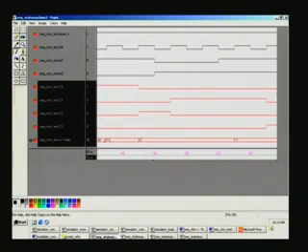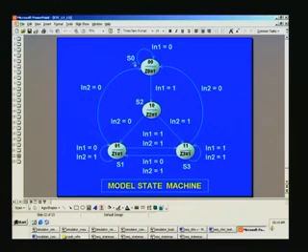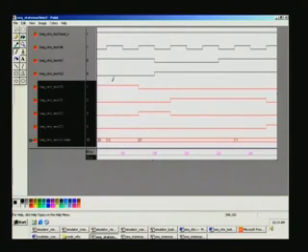So you can see, for S0, this is S2 here, right, this corresponds to the S2 state, and so on it goes. Now we will have a look at the actual state. In S0 you can go to the S2 state provided in1 is 1. So let us examine in1. It is 1, and irrespective of in2 being any value, it takes you to the next state S2 here, and the corresponding lamp also lights up here.